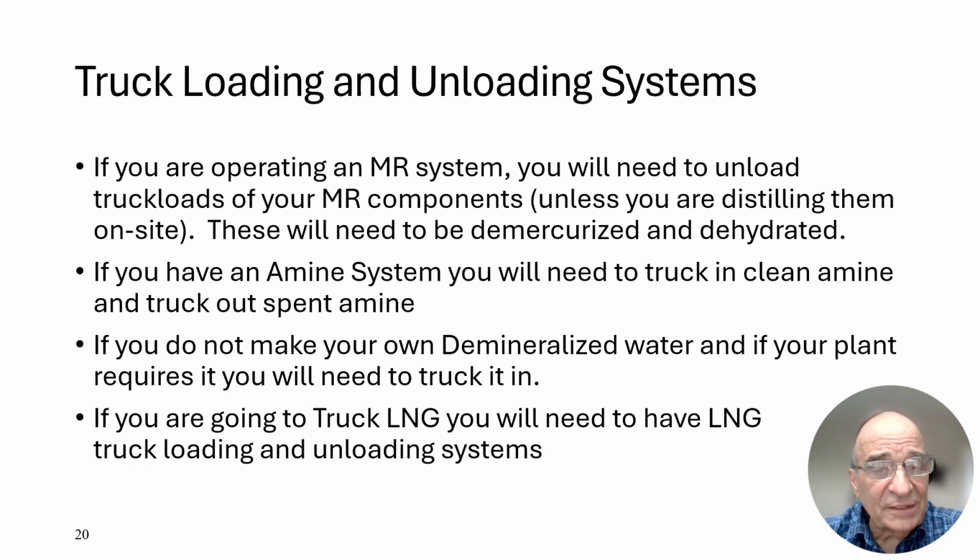If you have an amine system, you will need to truck in clean amine and truck out spent amine. If you do not make your own demineralized water, you will need to truck in demineralized water. If you are going to truck LNG, you'll certainly need LNG trucking capabilities.